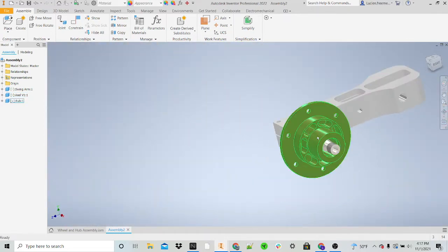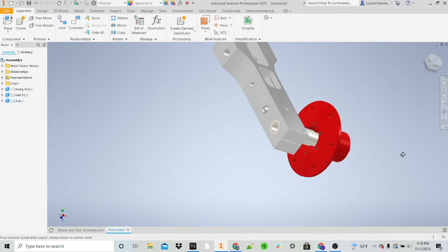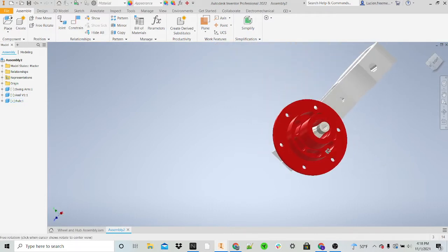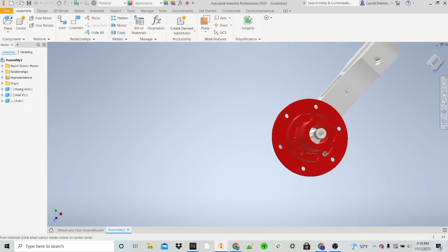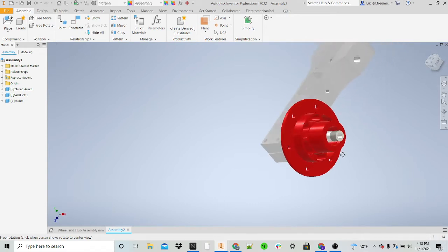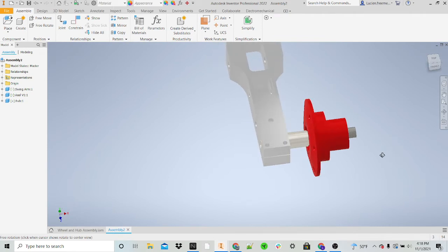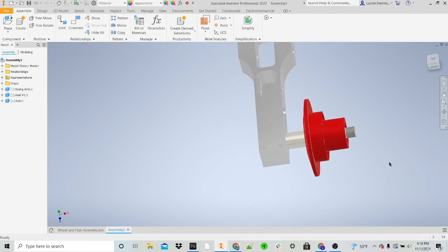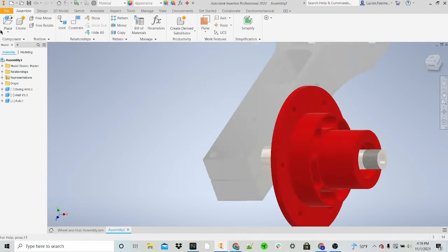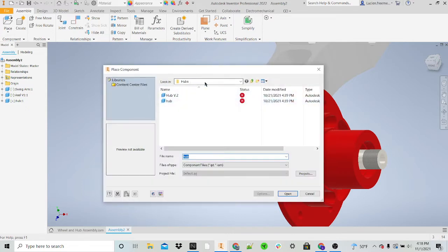Now, I don't know if you guys have ever seen a hub or changed a car tire, but it looks something like this. Essentially, this piece rotates along the axle, and then it is attached to the wheel via 6 bolts. And on the other side of it is the brake. What this allows you to do, which is a major bonus from what we have here, is rotate the wheel on the axle and remove it without having to take the entire brake unit and everything off and readjust it. So it'll allow us to make a tire change only around 5 minutes instead of the 25 minutes that we've been doing.